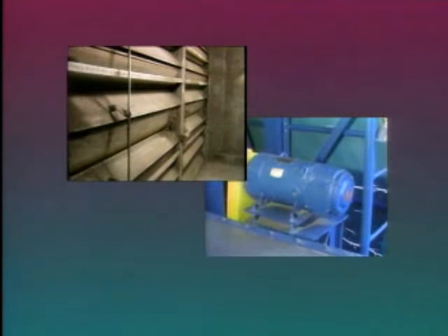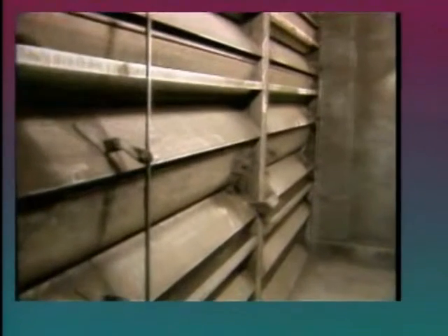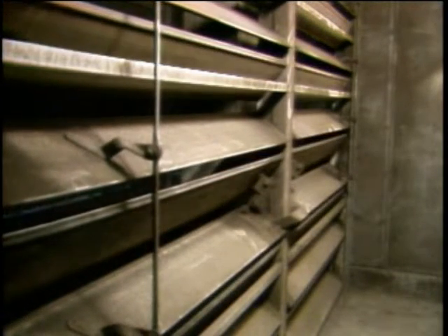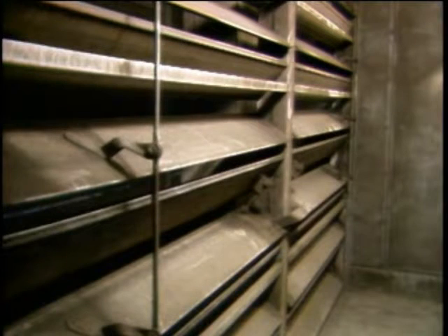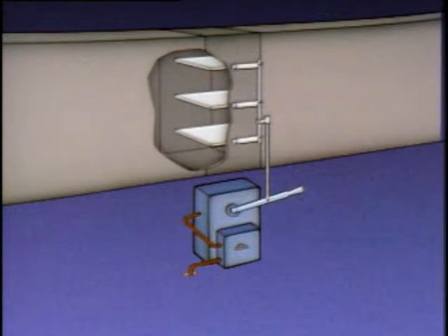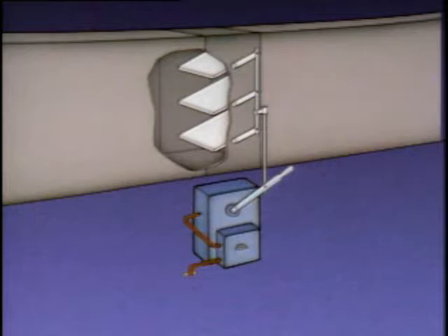In addition to valves, there are many other types of final control elements. Two of the most common are dampers and motors. Dampers, which are often called louvers, use a number of adjustable parallel vanes or blades to control the flow of air and other gases. In some systems, dampers have a pneumatic actuator with a positioner that controls the position of the vanes. During operation, when the positioner receives a signal from a controller, it supplies air pressure to the damper actuator. The actuator then opens or closes the vanes to position them according to the signal from the controller.